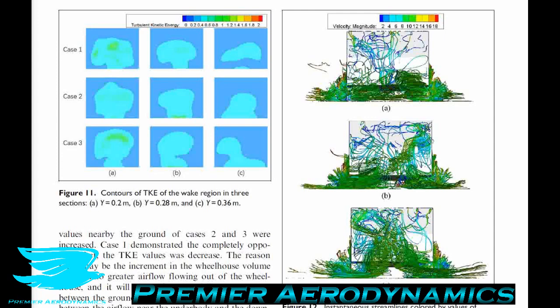That doesn't necessarily tell you the whole story, because it might look like one kind of figure at one point in time, but when you jump to the next point in time, the streamlines have changed dramatically. It turns out that maybe you just happened to see a good instant, so you got a somewhat warped picture, and you thought, okay, the flow is much more streamlined than what it actually is. So a time average streamline is usually more helpful, but instantaneous streamlines also have their place.